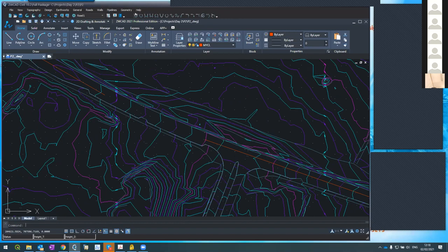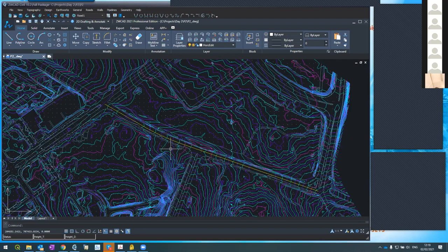It's called line length fit arc, fit curve. So line, he asked me, do you have a transition curve from here to here? I say 0. And everything I just press enter, because I don't know the radius. I just put a transition of 0 and the system will automatically use a default radius. Okay, since I entered 0 transition, there's only one solution, and this is the curve that the system creates for me between these two lines.